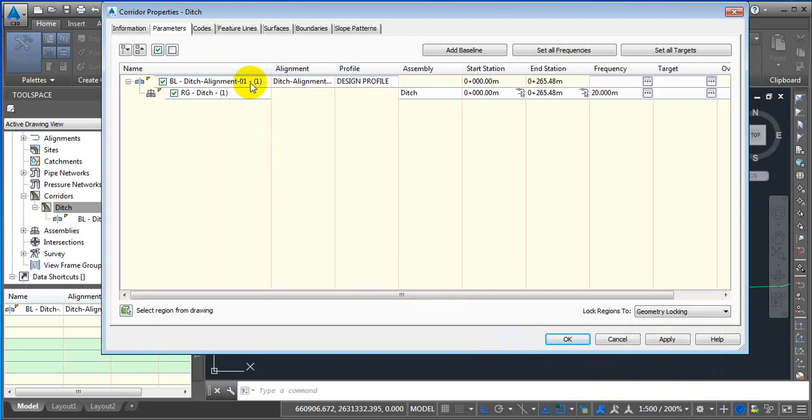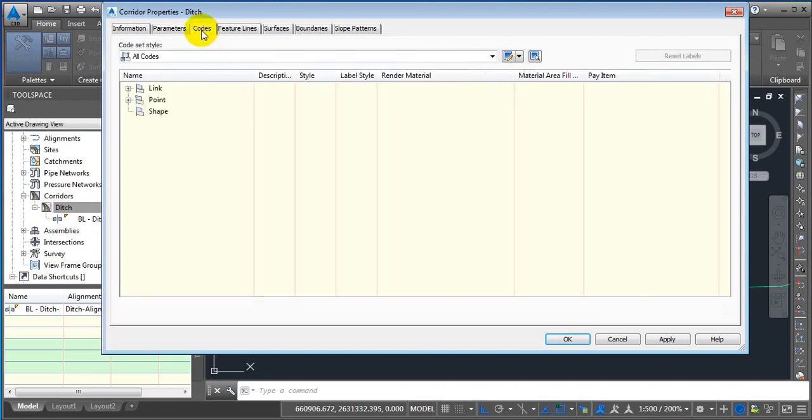First thing, we are gonna provide, let's just only show the top of the wall first. Then once we do that, then we will divide this corridor into 2 or maybe 3 parts, because in each part we will introduce new type of section, new type of drainage section. So to show the corridor or to make it visible, you just need to go to codes.